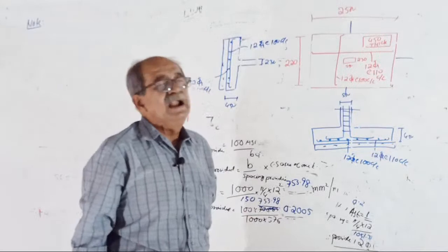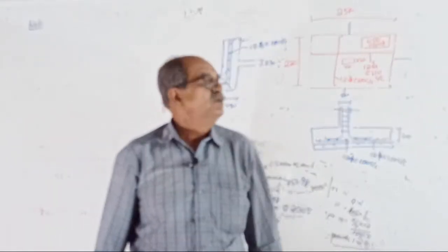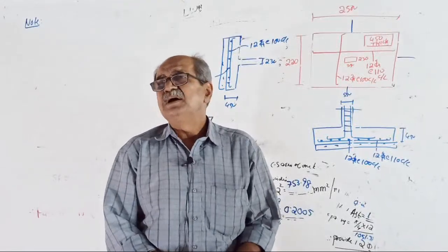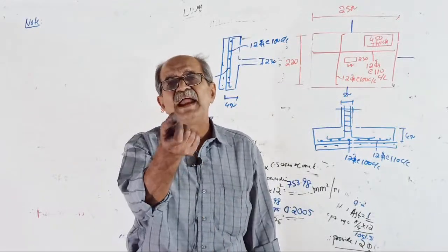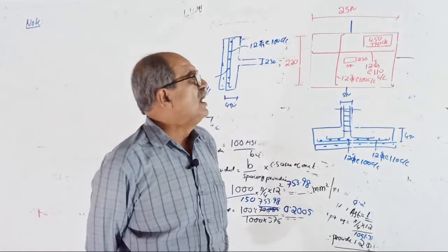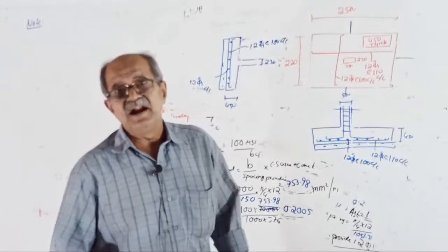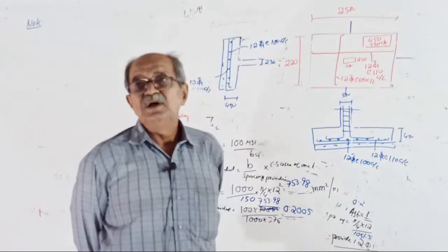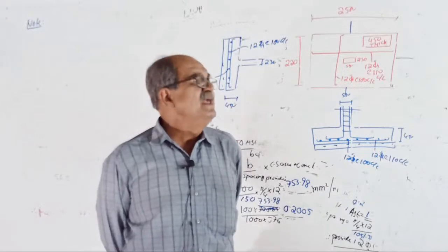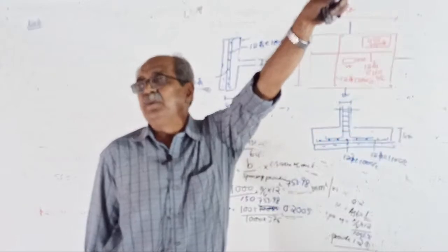Okay, one. Second point. Slab thickness you randomly give, because if unsafe, you changing will take few seconds. You try 400. It will tell not safe. 450. Not safe. 500. Safe. Over. So changing thickness is not a main issue. You change the property, you go to property, there define.